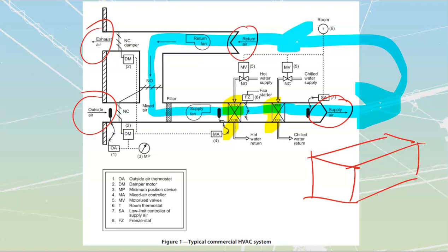We do also have another alternate route where we can divert some of the spent air, depleted of oxygen, with odors, dust, things like that inside of it, and we can take in fresh outside air to make up, as it's called, for what we've expelled out of the building. In a commercial built-in unit, we see this all done through the actual ducts that are going to be cut into the side of the building, those big louvers.